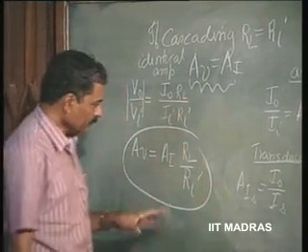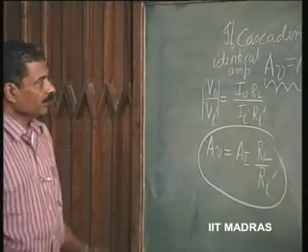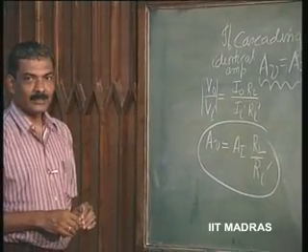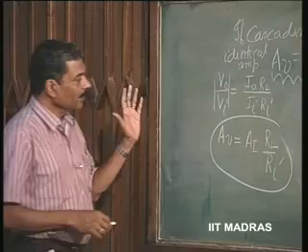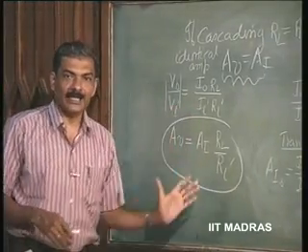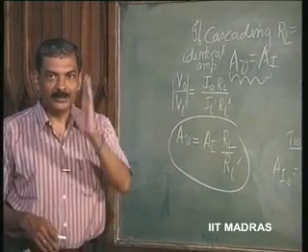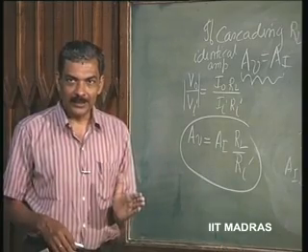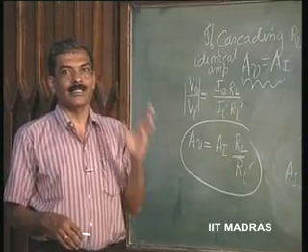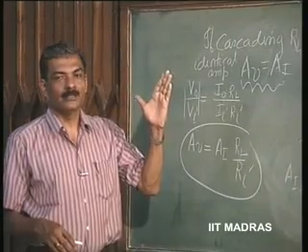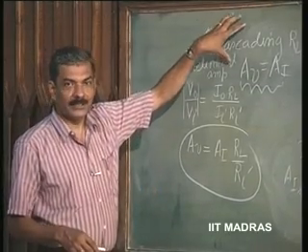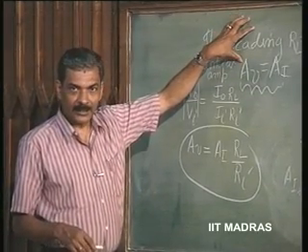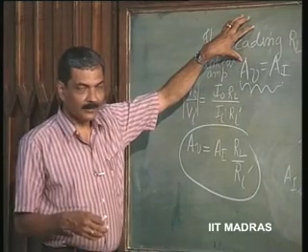So, if they are identical, its own input impedance is the same as the load. This is a common sense thing that you have to remember: when I cascade identical stages, the stage that I use must have both voltage gain and current gain. Then only it can act as a power amplifier. This is an important statement, profound in its effect on design.